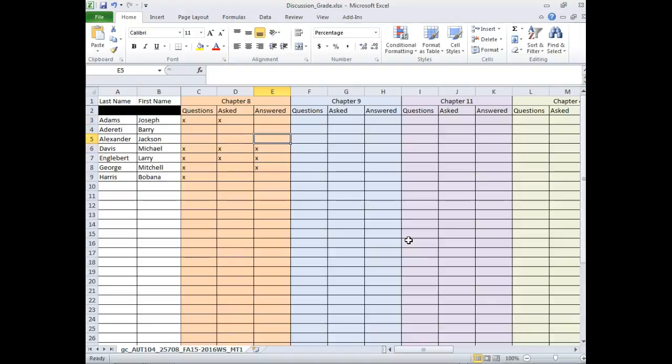So we have 2 types of thermistors. We have positive temperature coefficients and we have negative temperature coefficients. Positive temperature coefficient means the resistance changes in the same direction as temperature. Negative means it changes in the opposite direction. So if temperature goes up and resistance goes up, it's a PTC. If the temperature goes up and resistance goes down, it's an NTC.